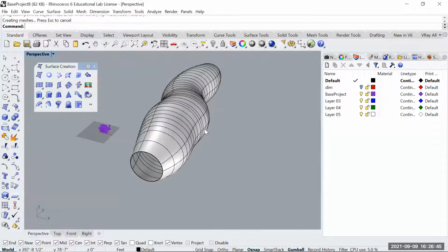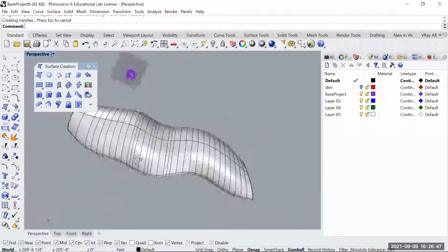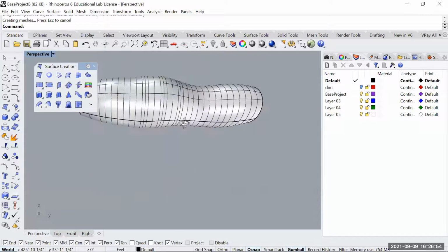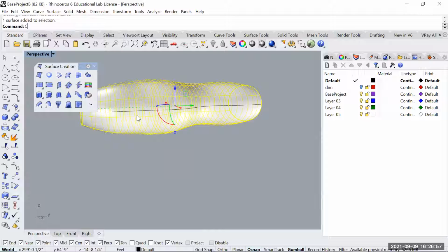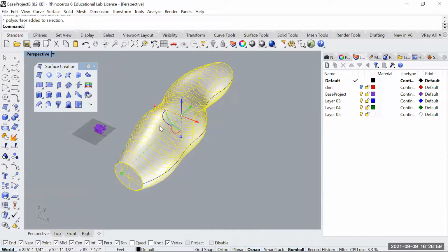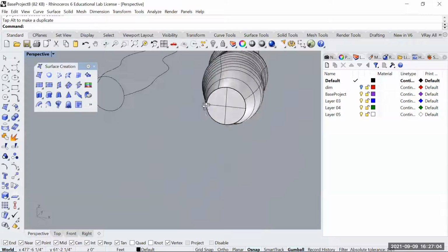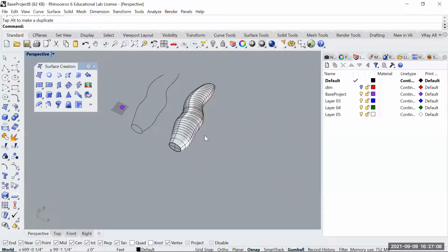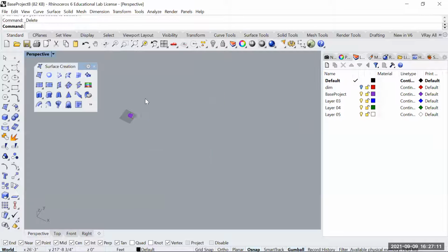There you go. So it creates this like weird irregular thing that you can't get with extrusions. You can't get with any other. You can't get with Loft easily. You know? So you can do a cap of this guy and use this as an element of whatever, a canyon or like a little cave environment or something like that. So that's sweep 1 and 2. And those are actually present in the first assignment. So if you want to try to get some of those sweeps and work with those, that would be fantastic.